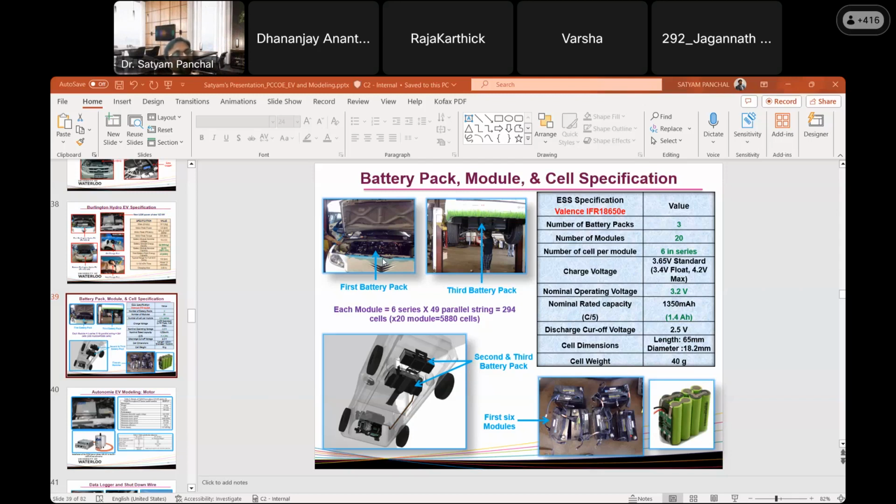Second, when it comes to air cooling versus refrigerant cooling, almost all OEMs are using R134a refrigerant based cooling, while Tesla is using passive air. Passive air doesn't have the drawback of lithium plating. I don't know whether you are aware of lithium plating, but other vehicles have their biggest issue with lithium plating because cells are placed in a vertical position and coolant channels are at the bottom. So cooling is only at the bottom side of the cell, and that is one of the biggest drawbacks of water cooling. That is why they are not getting enough range even during fast charging, because current is more towards the anode side. They have a big problem with fast charging.